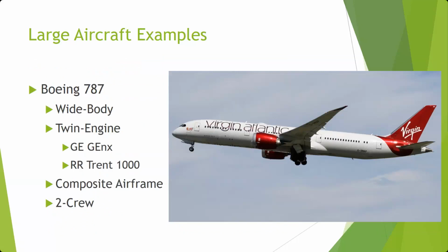The engines in airline world, or in transport aircraft world, are separate assets from the aircraft. It's not like your car or even like a Cessna or something like that. We played musical engines on the airplanes I worked on all the time. If a plane came in, needed engine work done, any kind of serious engine work done, it was not sitting on the ground while we worked on the engine. That engine came off, a different engine went on, airplane went out and flew, engine went to the back shop to be overhauled, taken apart, that kind of thing.